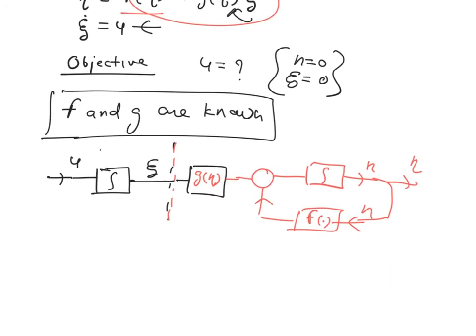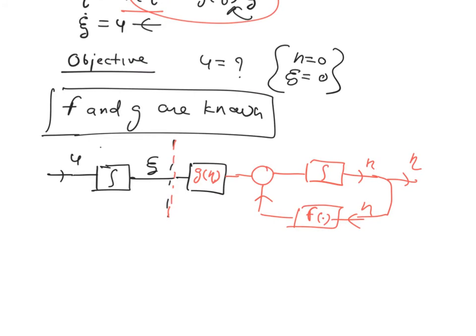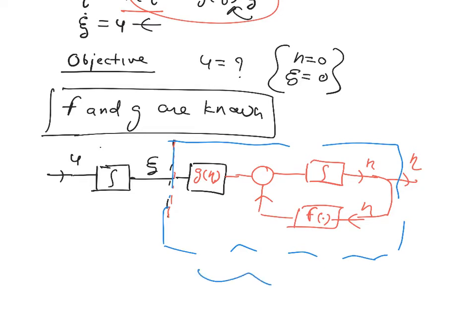If you notice, we can consider this like our cascaded control, or inner loop, outer loop. This is exactly that. This is one system, the inner loop system, and this is the outer loop system where zeta, for example, if you wanted to control the yaw, the input is phi, the roll angle. I don't know if you remember your UAV dynamics.